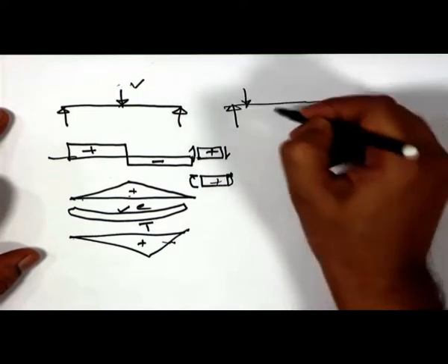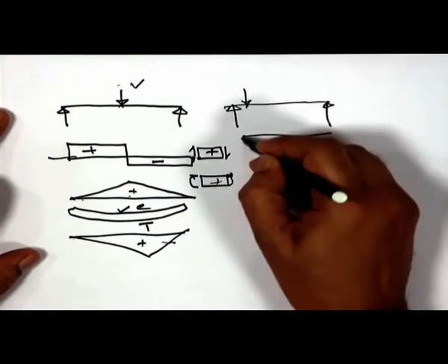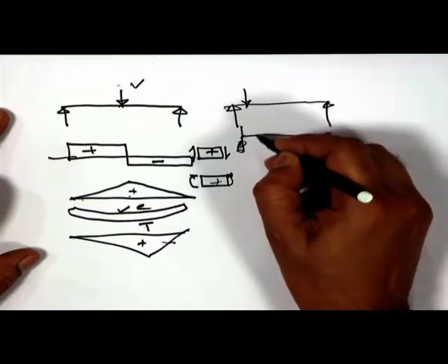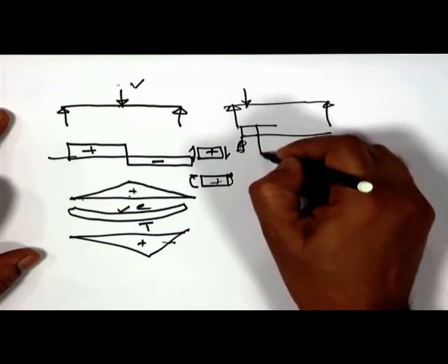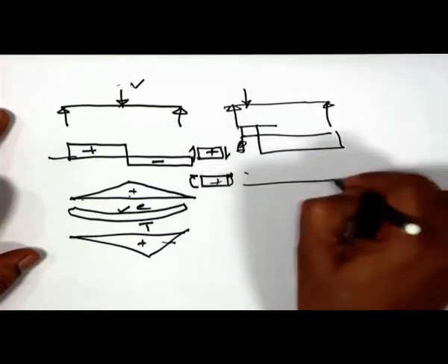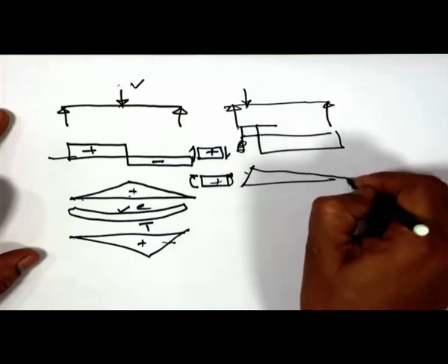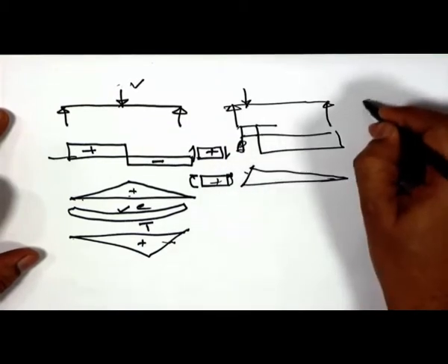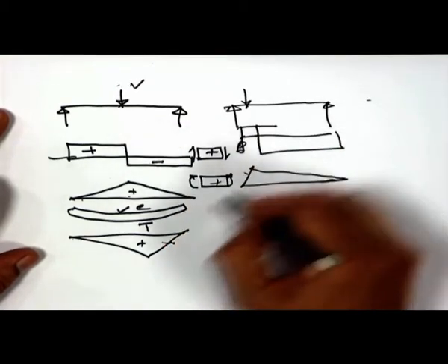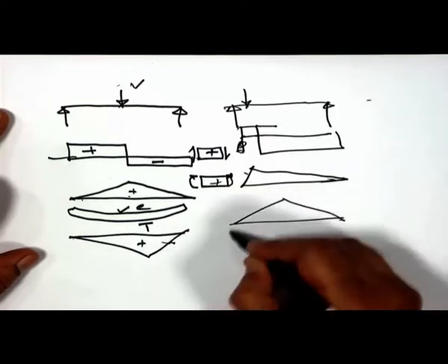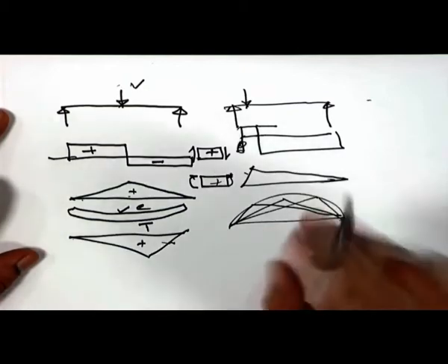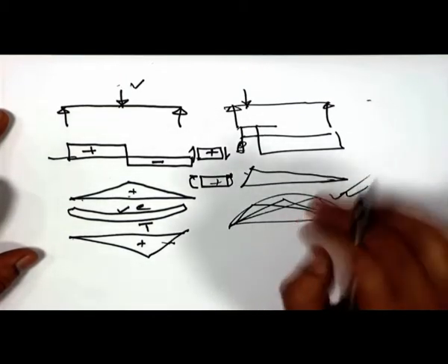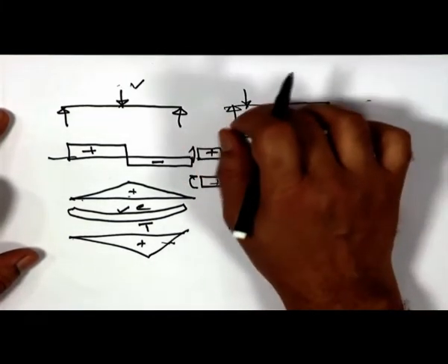You will place the loads at different locations, according to my sign convention. So, it is positive. Here the things will change, and we will have a different bending moment diagram. Similarly, for different locations, we will draw different bending moment diagrams, plot them together and try to find out the profile, how it is changing. All these things need to happen before I understand the effect of the live load.